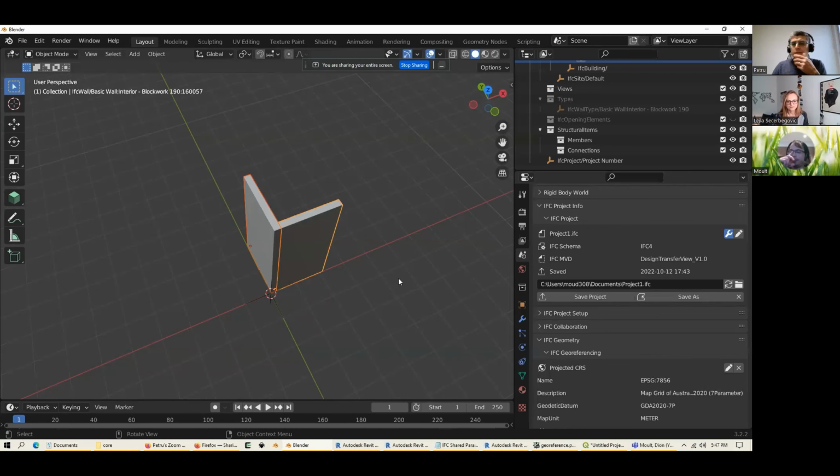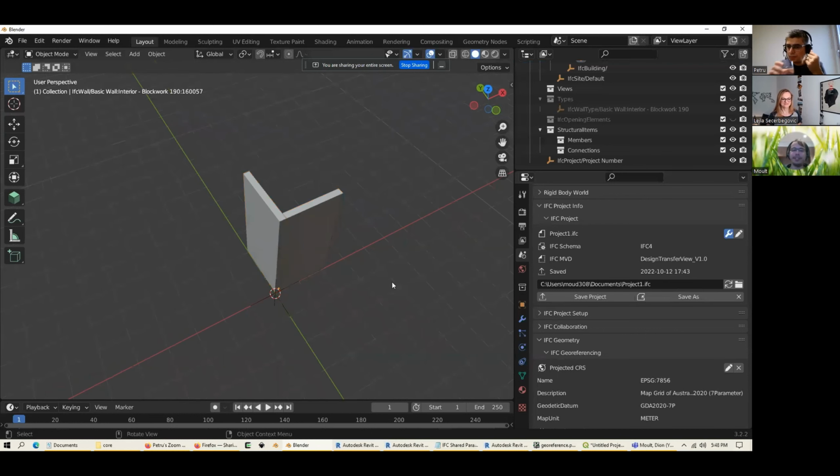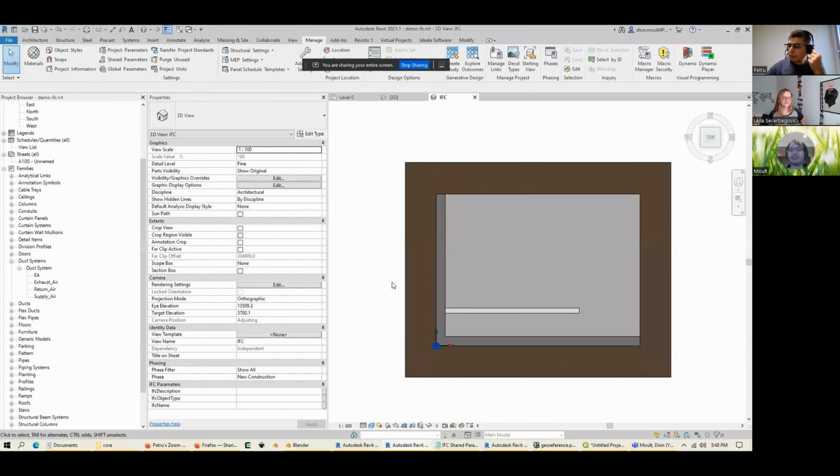So we talked a little bit in our first video on one of the most obvious differences, being the material layer sets, which are parametric, versus the non-parametric geometry, which you just alluded to in the more native IFC geometry editing. Our particular topic today on georeferencing, it shouldn't make any difference which IFC4 MVD you're using, but that's an absolutely great point, that the development focus by Autodesk is more on the reference view. It still doesn't change my personal opinion on which one we should be using, but it's very good to mention where Autodesk's priorities currently lie.